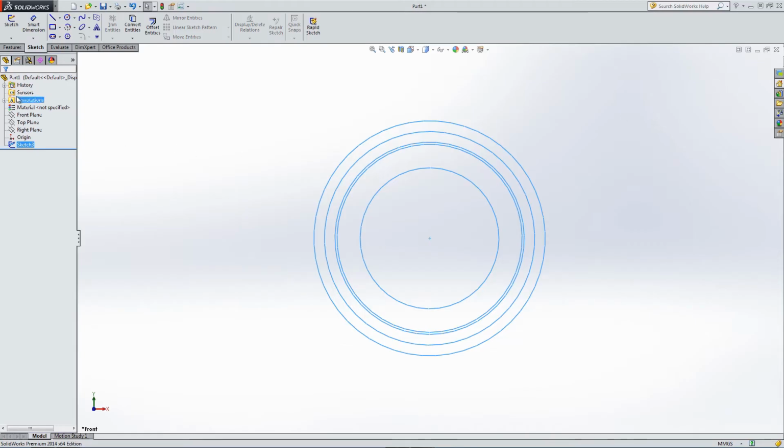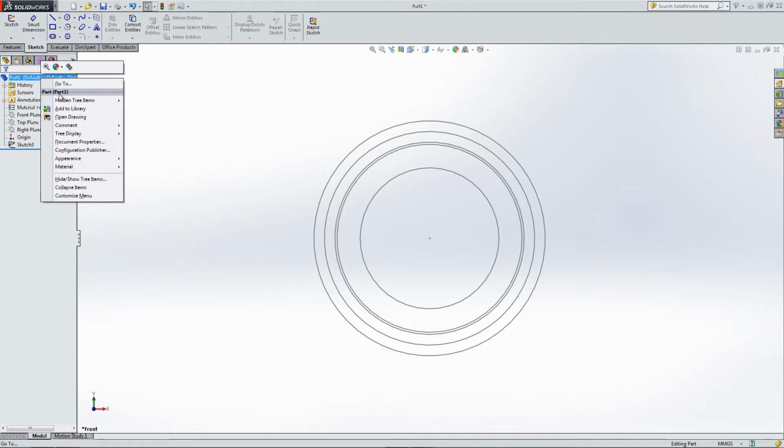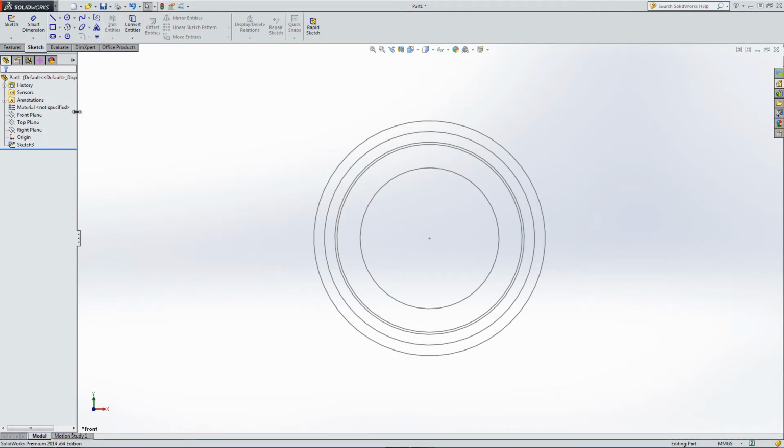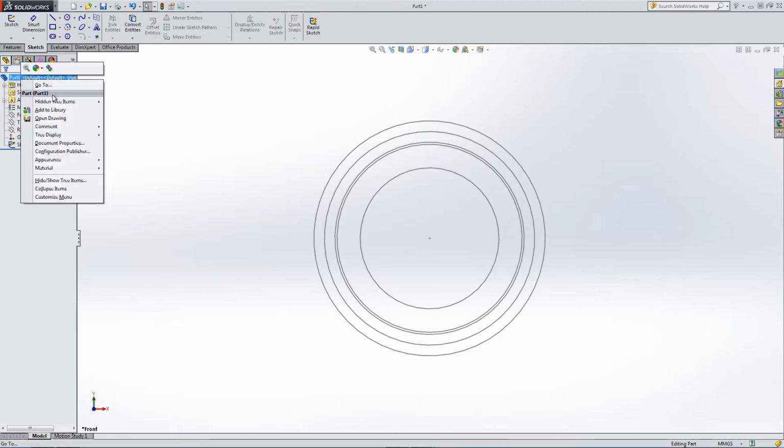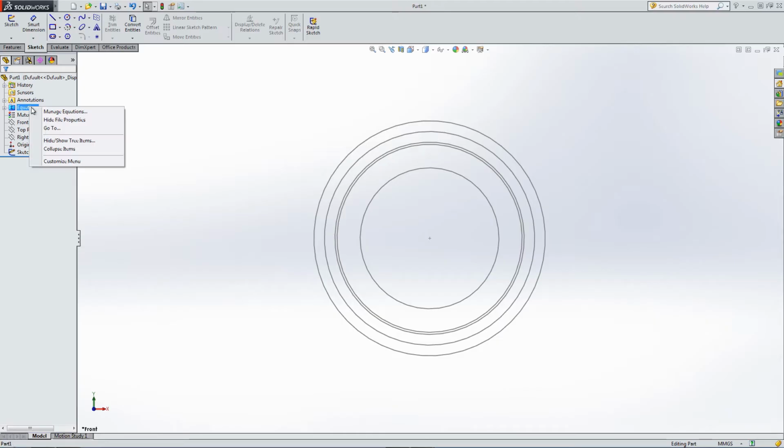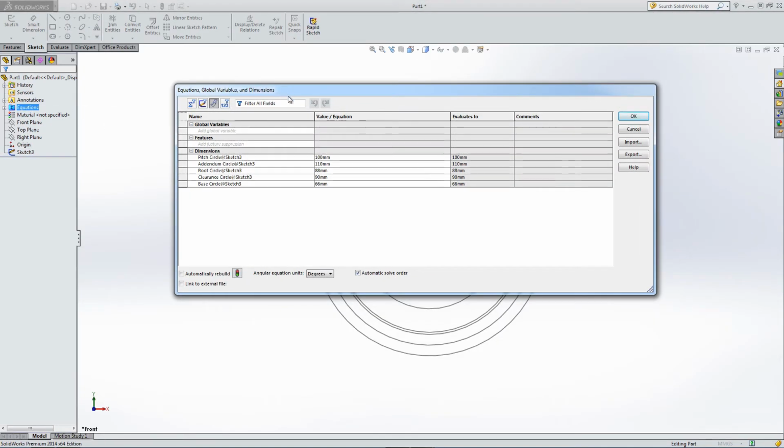We've completed our first template sketch, so now we can go into the equations toolbar, but first we've got to unhide it. So equations, show file properties. Oh, let's try that again. Equations can be tricky. Show file properties. Okay, so here's equations. Right click, manage equations. Let's bring them on the screen. So everything we've labelled up so far with a dimension is shown in the dimension section.